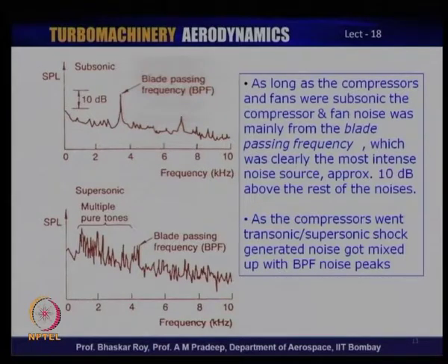So, in modern engines the 10 dB gap or safety margin that we had is gone, because there are so many other frequencies at which high noise is indeed happening. Some of them are indeed higher than even the blade passing frequency. So, the noise coming out from axial flow compressors or fans, the modern ones, is indeed of multiple tones, and they are of course more difficult to contain.